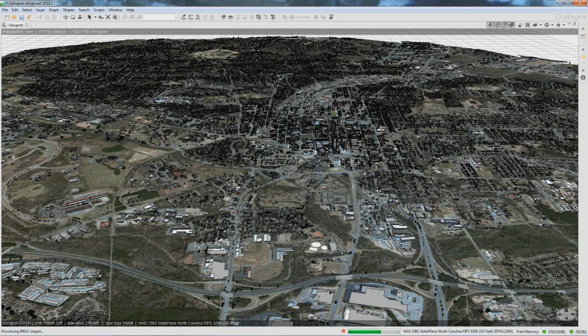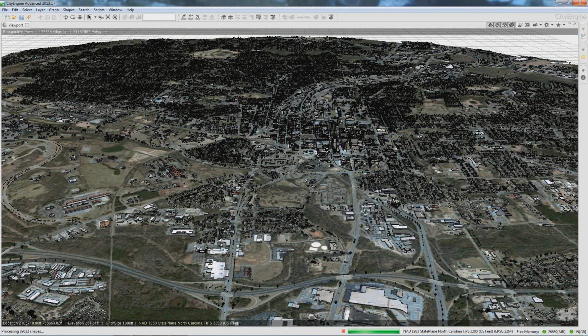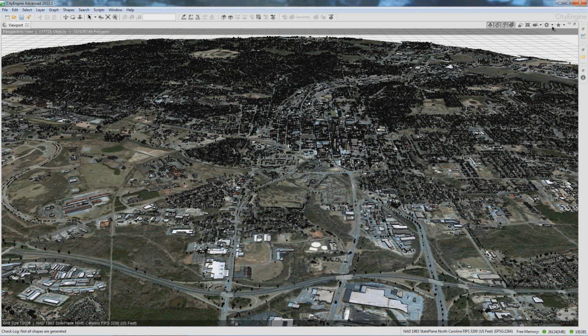But where we didn't have building footprints, we could collect height information, roof slope information, and roof type information directly from the LiDAR data sets and apply rules to the building footprints with those attributes from the LiDAR to regenerate how the city looks. So this leverages authoritative data to help recreate the existing conditions in a very quick amount of time.